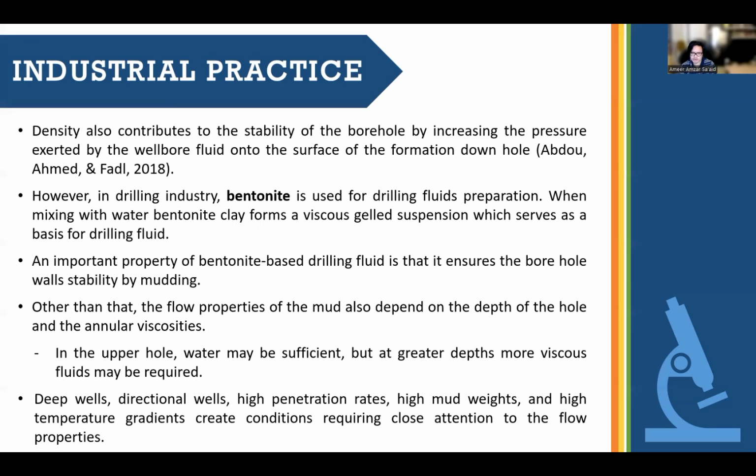A specific feature of bentonite clay as a natural material is that it is environmentally friendly. Other than that, the flow properties of the mud also depend on the depth of the hole and the annular viscosities. In the upper hole, water may be sufficient, but at greater depth, more viscous fluid may be required. And lastly, deep wells, directional wells, high penetration rates, high mud weight, and high temperature gradient create conditions requiring close attention to the flow properties,